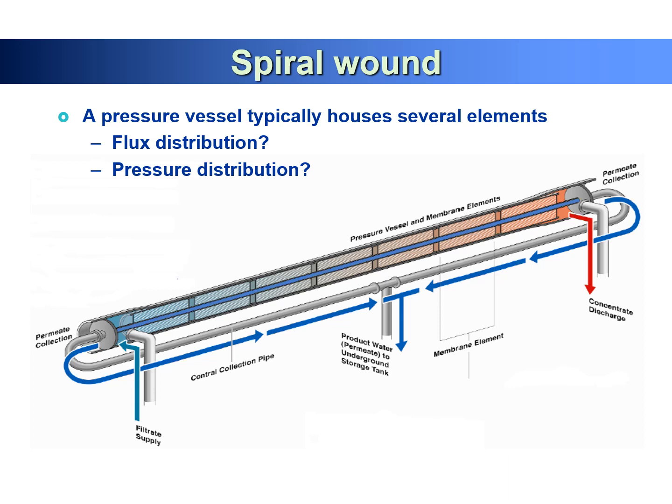So let's look at the pressure vessels. What's the typical water flux distribution and pressure distribution? Seawater passes through each element, so the concentration of your feed water keeps increasing, and you can see the red color, which is the concentrate discharge point. When you have a high salt concentration, because of high osmotic pressure, your flux will decrease at the end of your element. So initially you have a higher flux, then lower water flux.